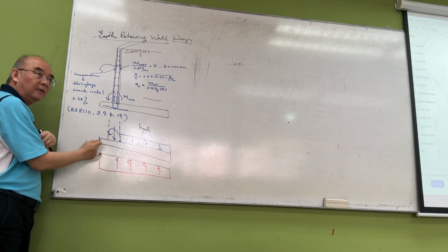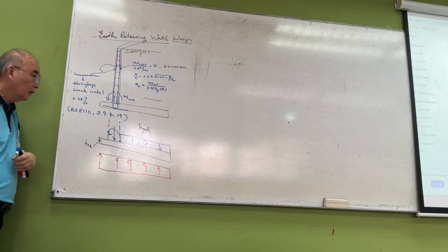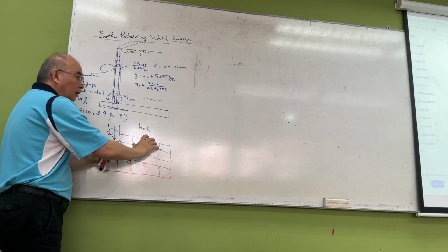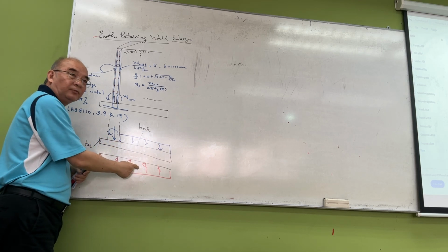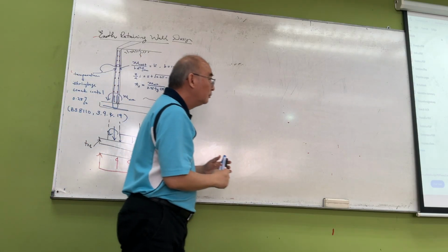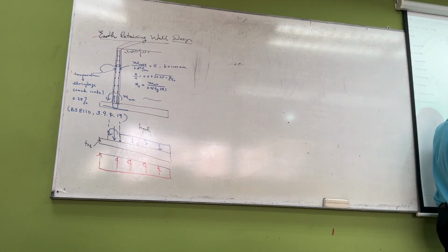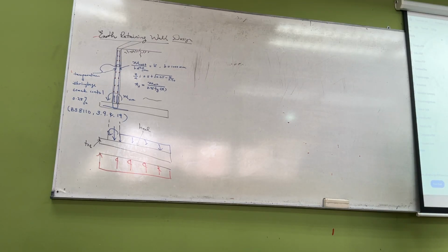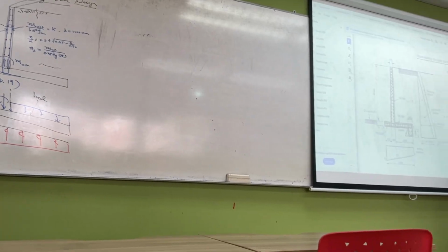Okay, understand? Here, because here is relaxed. Normally this one here is much bigger than this one. So here your tension side is on the top. And because this is a much longer cantilever, you can see that it's a T20 at 200 as compared to this one, which is T12 at 200. Okay? Understand? So this is the basic concept.